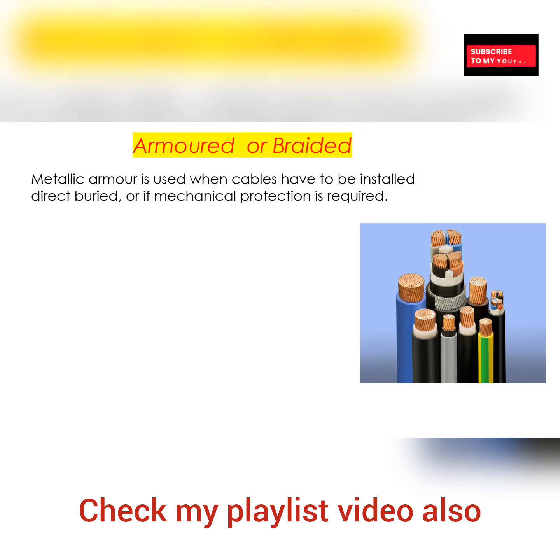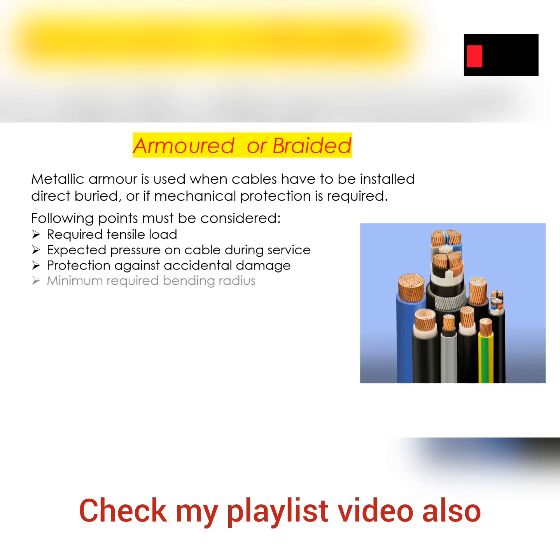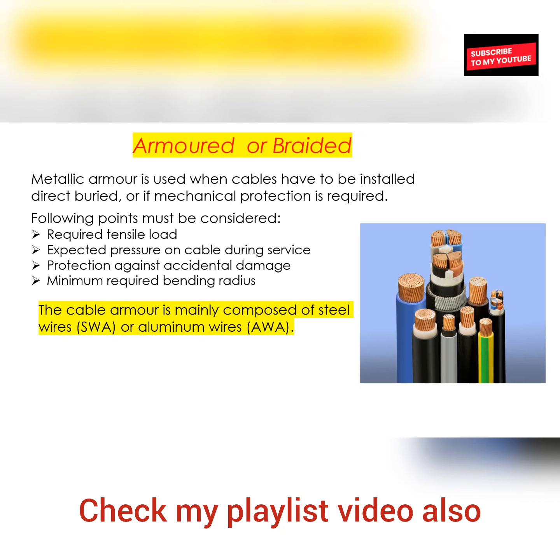Metallic armor is used when cables have to be installed direct buried, or when mechanical protection is required. That's why it's very significant that we utilize this kind of cable, especially in the oil and gas industry. The following points must be considered: 1. Required tensile load. 2. Expected pressure on cable during service. 3. Protection against accidental damage. 4. Minimum required bending radius. And we have another one.